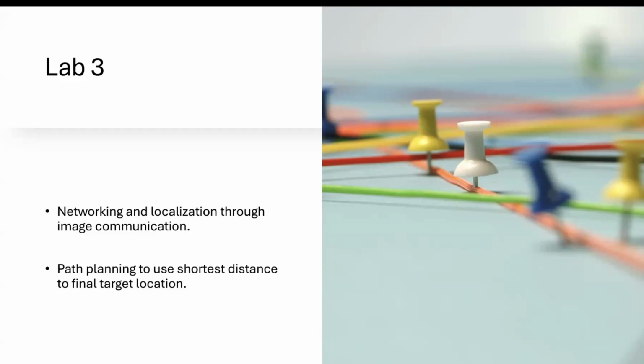To do this, we established an SSH connection between our JetBot and a stationary camera bot that was mounted in the ceiling, so the camera bot could provide a bird's eye view of the entire roadmap. Before we could do any sort of navigation, however, we had to perform some camera calibration to correct the lens distortion, as well as to have the correct sizing for these different positions and distances.